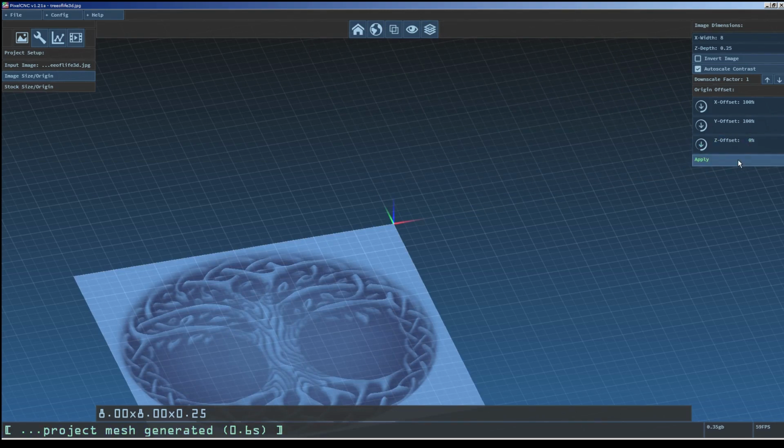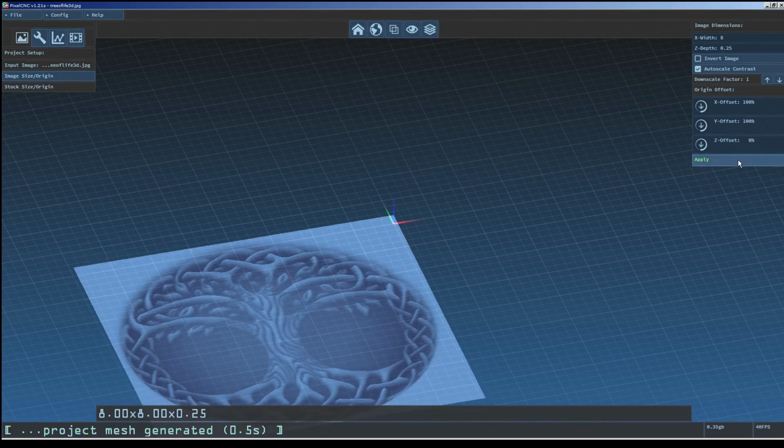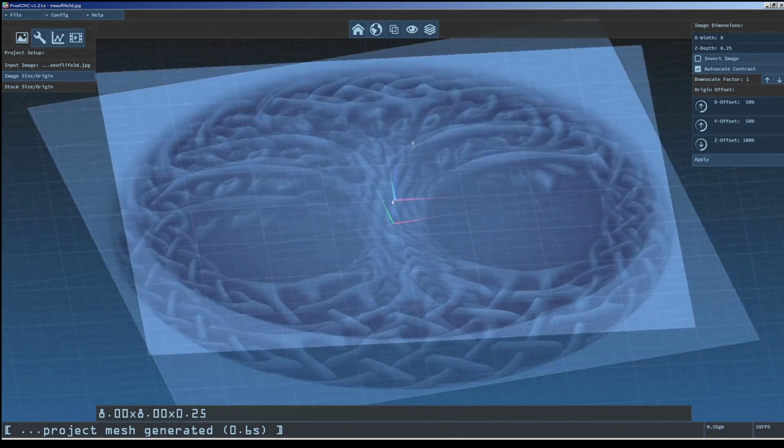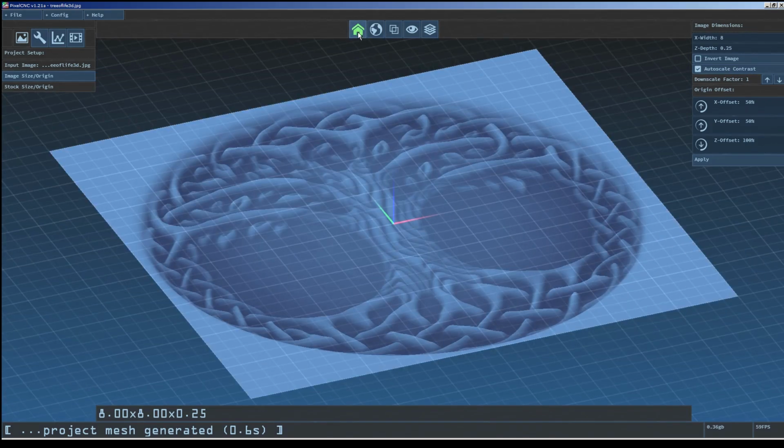This makes it easy to set the origin to the extremes of a project's dimensions, or any fraction in between, such as 50% for the middle of a project. We find the top dead center to be the most useful because it allows us to ensure that toolpaths will not be too close to one edge or another. As long as the machine origin is zeroed at the exact center of the stock, we can trust that our cuts will be centered on our workpiece as well.